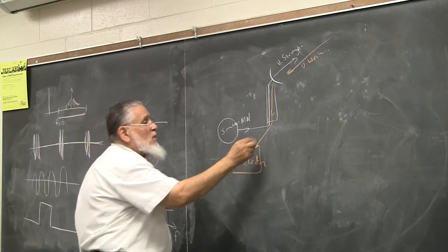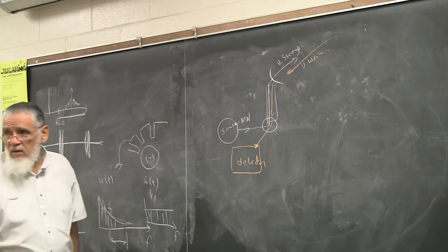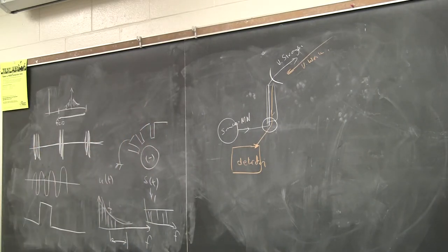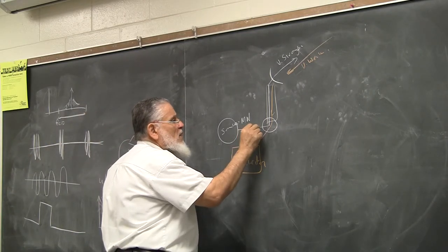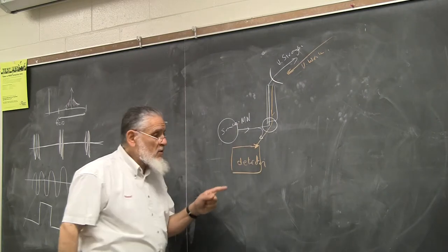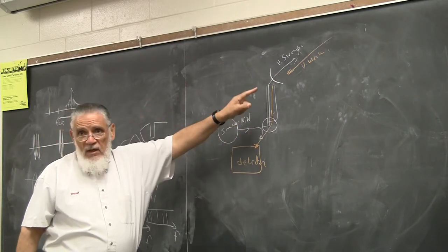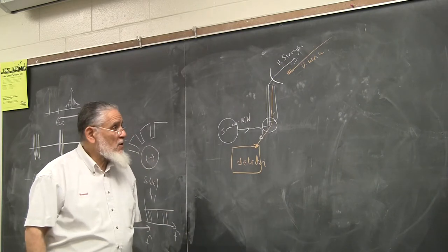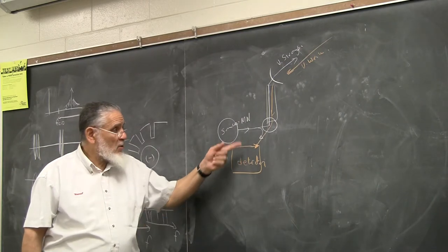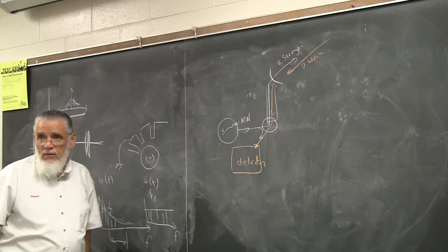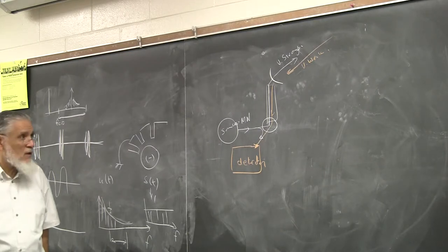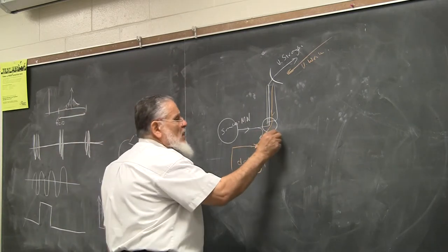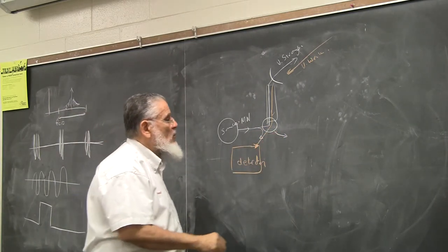So what do we do here to make sure that we are okay? Because basically, if a small portion of the signal leaks into here, it's going to overshadow your signal coming back from the reflection. In addition, it may be too strong and burn your detector. You try to increase the sensitivity of that detector a great deal to be able to detect these very weak signals. This issue is typically handled through what we call the circulator.